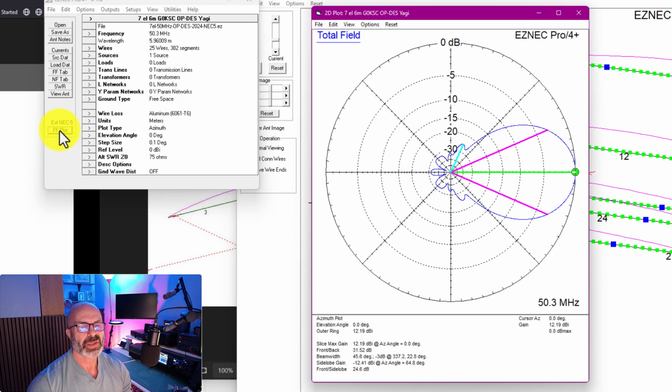So in an ideal world, that's what you're going to get and that would be how it would be with the most perfect of baluns. The choke is a nice simple one, but it's not always the most effective. Some of the baluns, as with the one that we discussed in the last video, work extremely well to get a much closer representation to what we're seeing here.